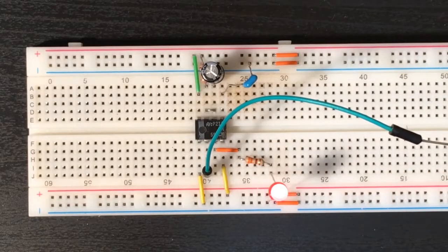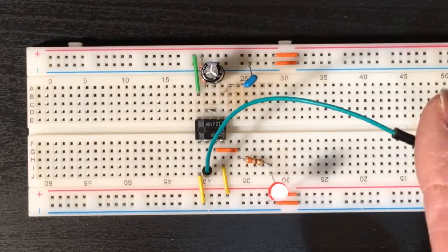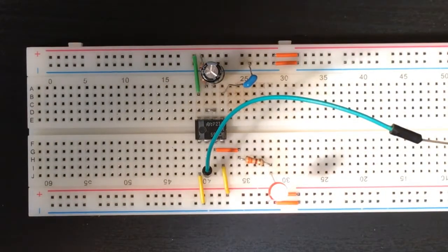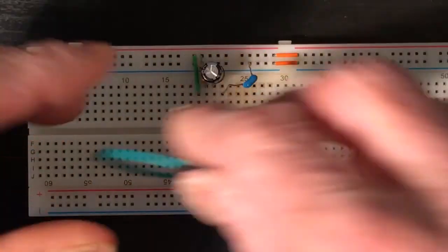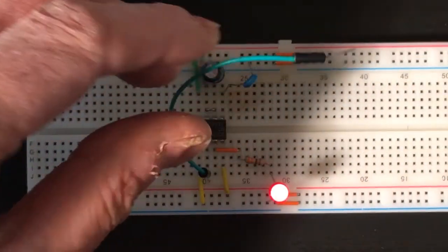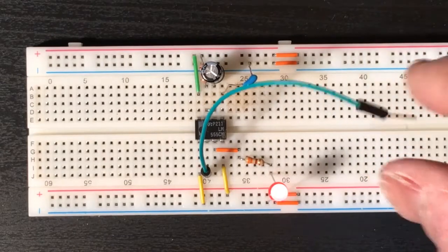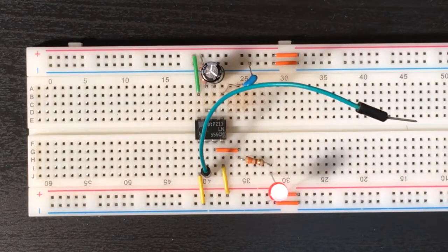Now here's something really neat. If you leave the trigger floating and you give it a long enough time period, you can make it act as a touch switch. So in this example, the only thing I've done is to take the switch out and simply use a wire attached to the trigger as the touch sensor.